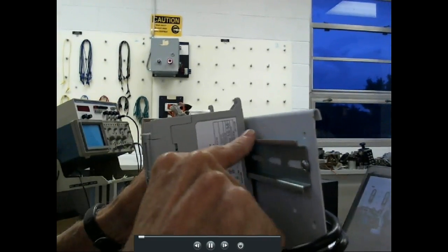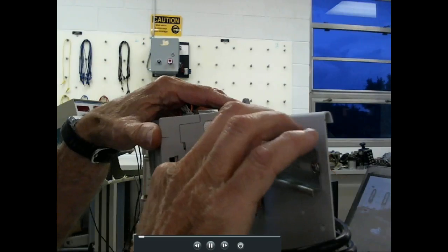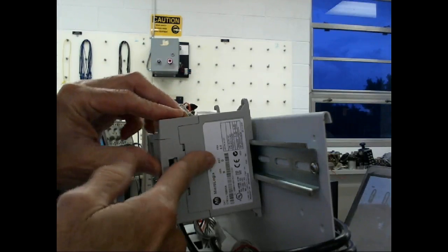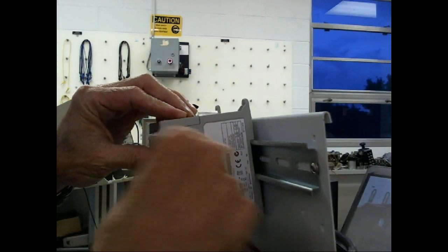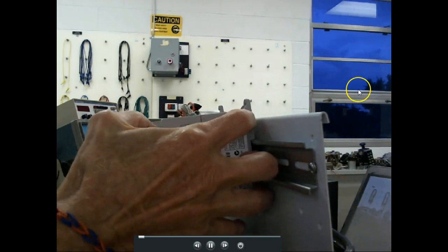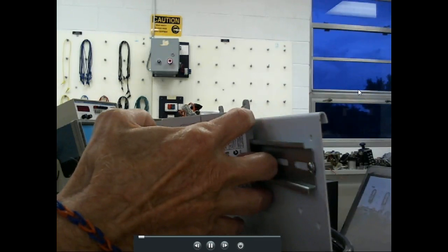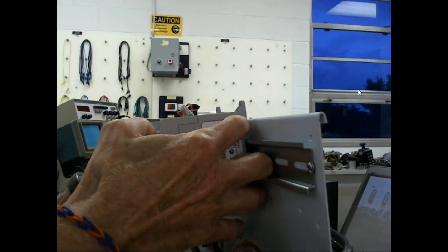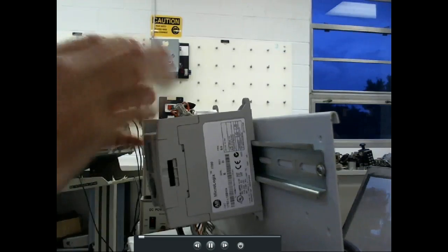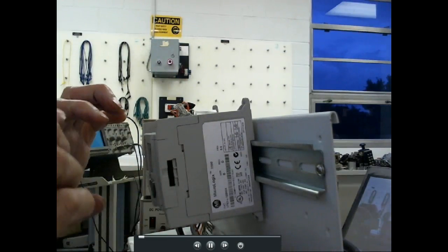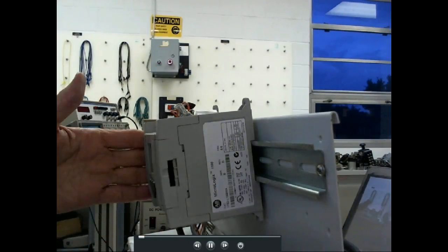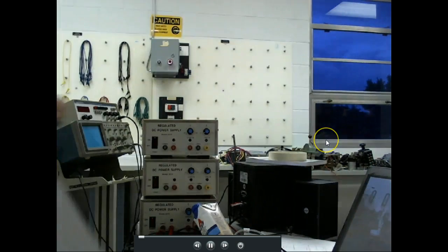So this is called a DIN rail, guys. It doesn't really stand for anything. This is a standard mounting system that we're using a lot in controls. You'll see this big slot in the side. Well, I can break this open, but I'm not going to do it. That's going to be the expansion bus right there. So I buy the module and I just slide it onto the DIN rail and snap it into the backplane. So we're getting away from the chassis. I call them hybrid PLCs because they come with a set number of inputs and outputs in the PLC itself. And then if you need to update, you can add more modules.